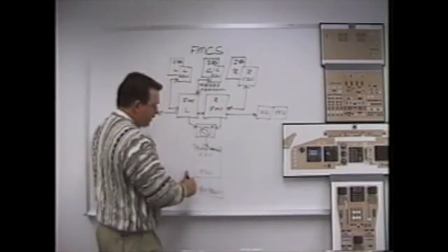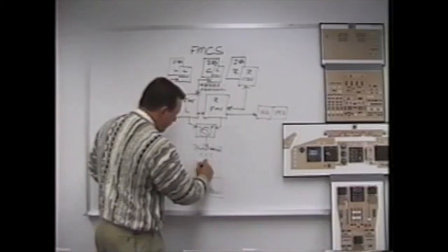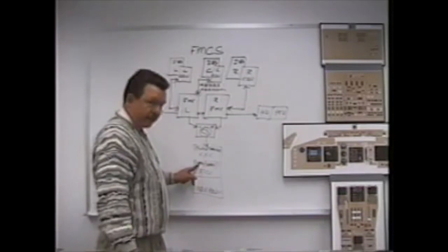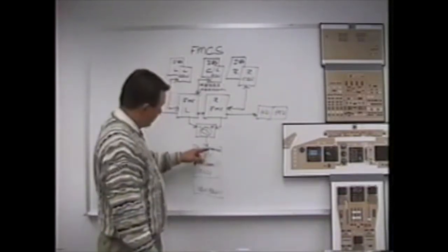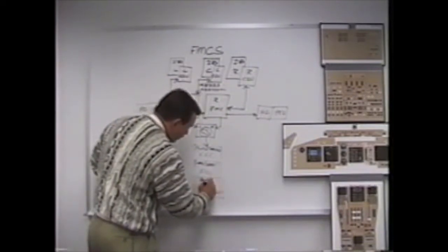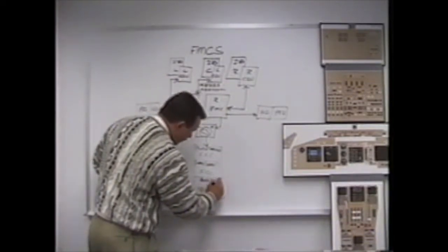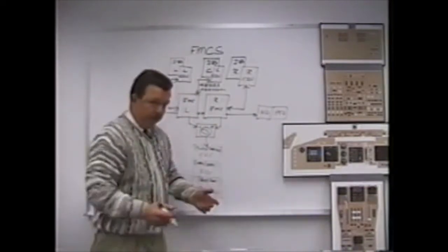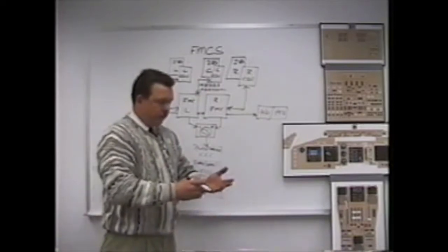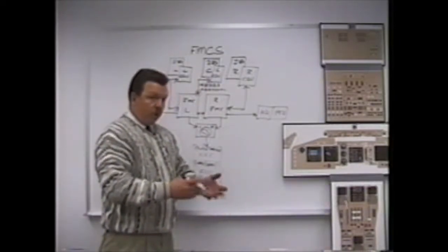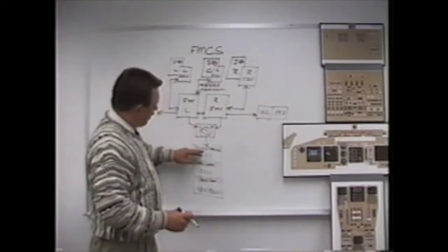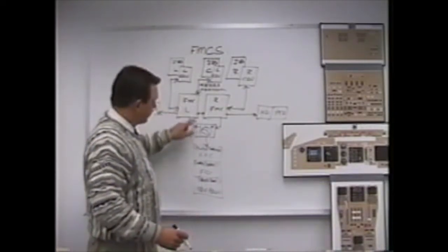Flight control computers, specifically what they need is the LNAV and VNAV signal from the FMC. When to turn left, when to climb up. And when I climb, set climb power. The nav radios, what to automatically tune them to, auto-tune. So if you don't have the nav radios manually tuned, the FMC is able to tune them. The FMC will automatically tune them based on a route, a procedure, or automatically for updating purposes like we talked about. But the auto-tune, the LNAV, VNAV, and the auto-throttles get their signal from the selected FMC.